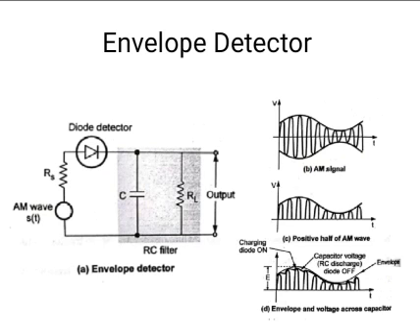Next, envelope detector. This is one of the types of amplitude demodulator. An envelope detector is a simple and highly effective device that is well suited for the demodulation of narrowband AM wave, for which the percentage modulation is less than 100%. In an envelope detector, the output of the detector follows the envelope of the modulated signal. Hence, the name envelope detector.